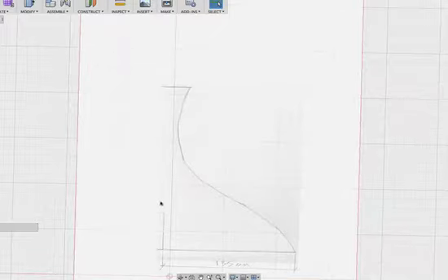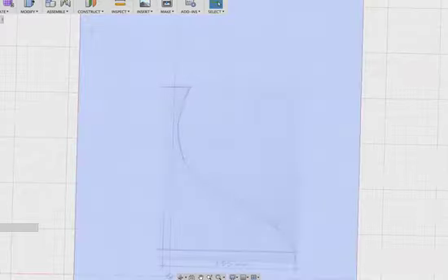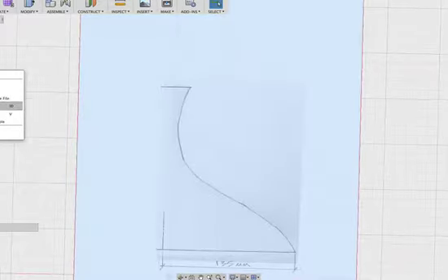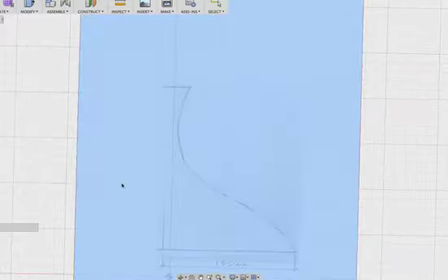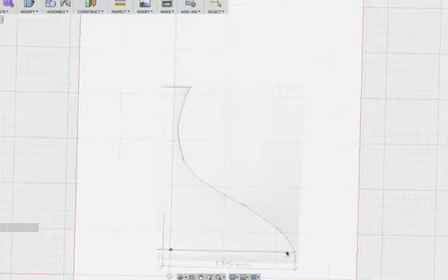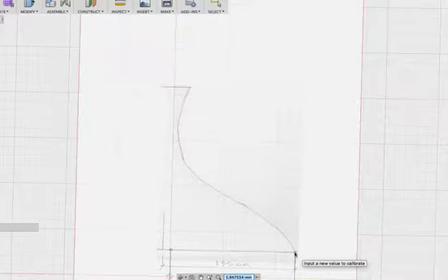Now, I'm going to first make this big enough. So I'm going to right-click on Shade Profile, and I'm going to hit Calibrate. Because on our drawing, it says 135 centimeters or millimeters. Looks like it does. Click there. Click over to here. And it says, oh my gosh, you only have 6. Right there it was 6. So right in there, I'm going to type in 135.